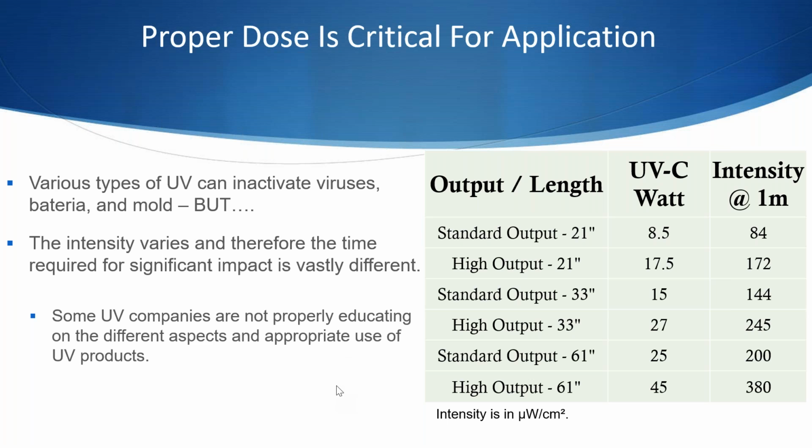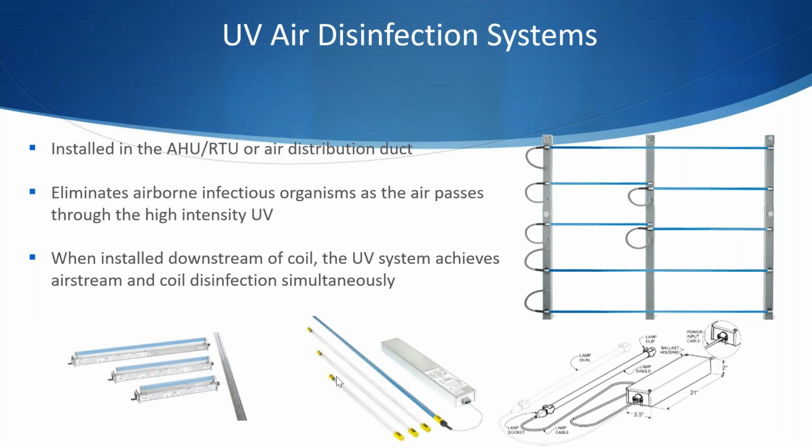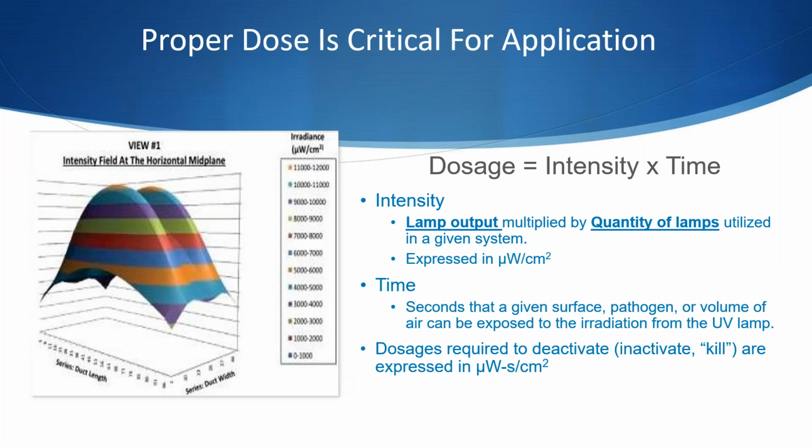Let me see, I need to go back. That's okay. I was going to get a better picture of it. Your first look, so to speak, that light shining, its first pass onto the airflow is a high level of UV, and that's the most critical part of the dosage. But then every reflection back, so like galvanized is about 57% reflective, whereas stainless steel is about 28% reflective. So that 57% is considerably more reflective.